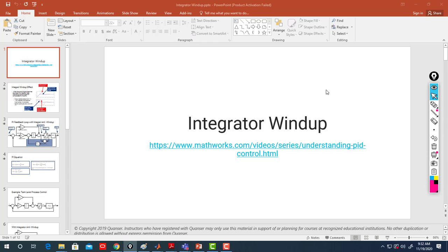Sensor measurements are usually noisy in practice. So when you have a sensor, it's not perfect, so it's noisy. Then when you add a derivative, it will amplify the noise. That's why a pure derivative is something we cannot implement physically, so we need to add a filter to filter the noise. In your design, think about the number n in your PID, which you also need to tune.